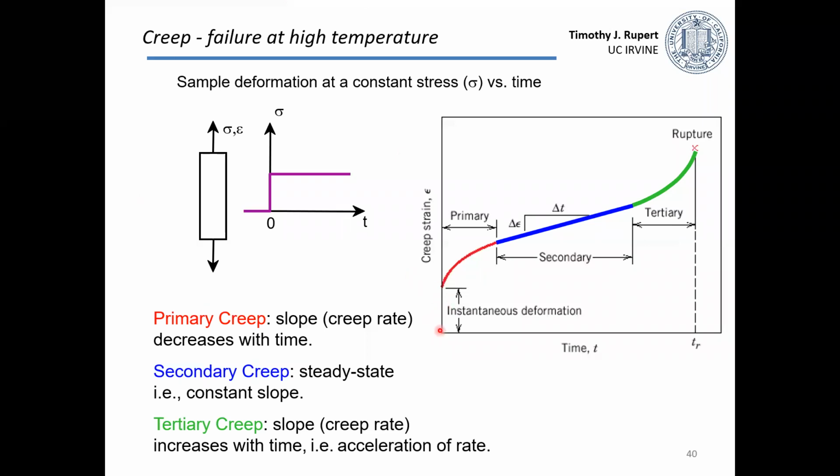So maybe that's that mixture of elastic and plastic that we have. But if we let the sample sit there, we'll find that it will keep elongating. And it will follow this type of shape where it happens relatively fast. There's a sort of what we call a steady state or secondary type of creep. And then finally, it ends up running away and fracturing.